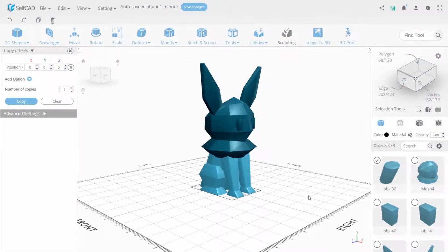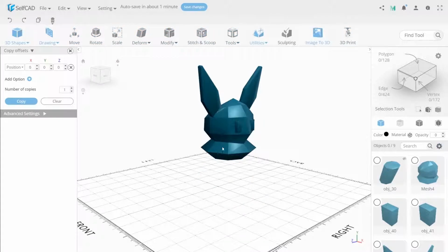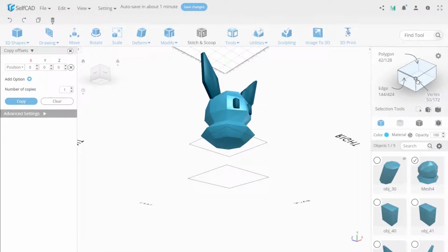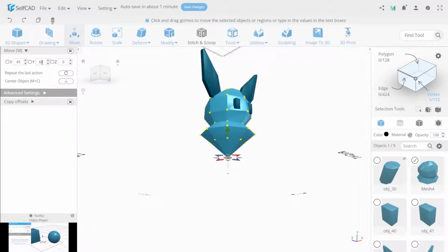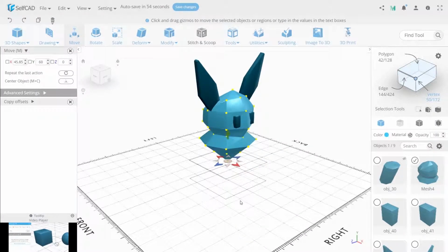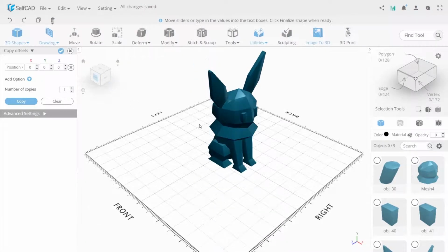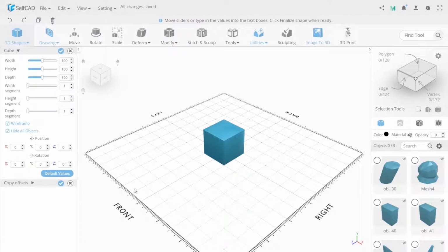Then select the whole body with legs and click Height. Open Vertex selector and select the bottom vertices and move them by 60 on the y-axis. Then click the View tab and show all bottom.